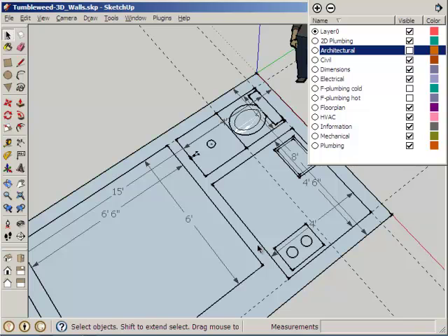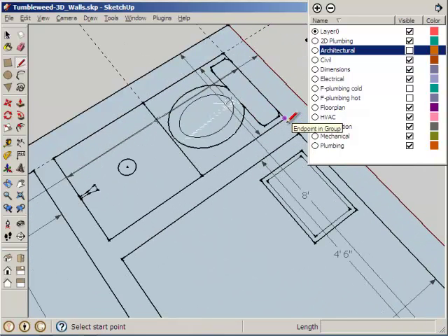So, in order to make this interior wall, there are a number of ways to do it, but for very simple walls like this, I'm going to use the line tool. I'll start arbitrarily up here, and my line tool is snapping onto the corner of the bathroom floor plan object. Click once, drag, it snaps onto the kitchen object. Click once, and now I have a line. And if you pull the line tool out, then you can see that it is now extending a new line.